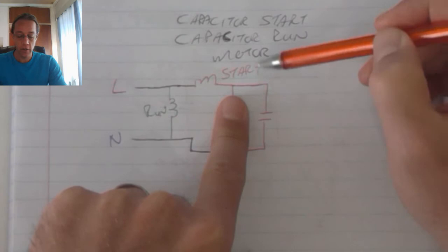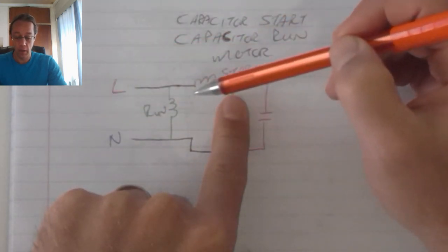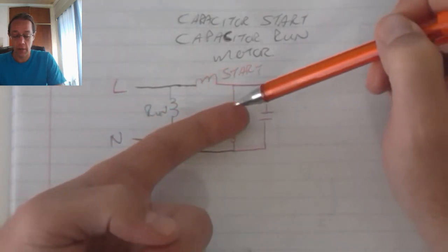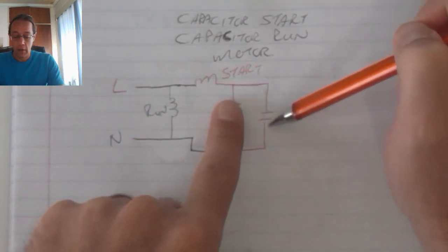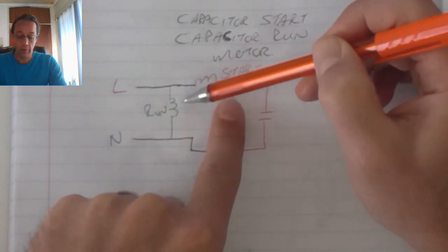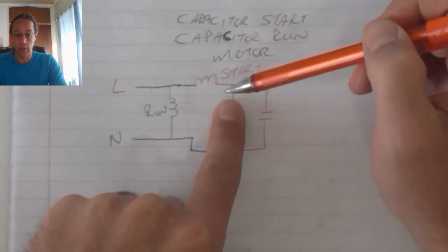Now, in ideal conditions, when this circuit is running at optimum speed, in other words, the centrifugal switch is open, that disconnects that capacitor. This capacitor, along with these two inductors, will allow the circuit to run close to resonant frequency.